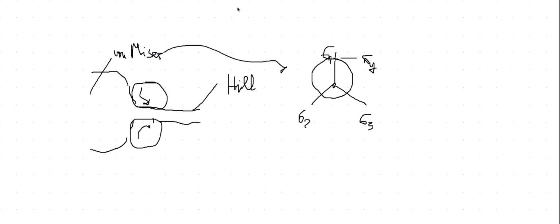And then for Hill criteria, people, instead of a circle, are making an ellipse, something like that. They are typically measuring yield stress in this direction, then yield stress in that direction, and they consider some kind of ellipse instead of a circle.